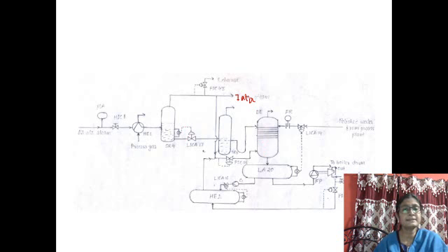So this is the method of choice of the final control element. And for the controller type, mostly all controllers are PI type, proportional and integral, except if there exists any slow process. That means for a temperature system, since here no temperature control loop is there.